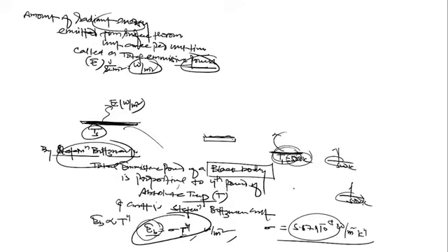Although it's made of the same material, when one surface is rough and one is smooth, the radiant energy emitted at the same temperature is different. It means the emissive power of any surface depends upon what? The nature of the surface as well as the temperature of the surface. Along with the temperature and surface, it also depends upon the material of construction. Even if the material of construction is the same, the nature will be different, rough and smooth, so the rate of energy emission will still be different. Is this clear, Mr. Praveen?